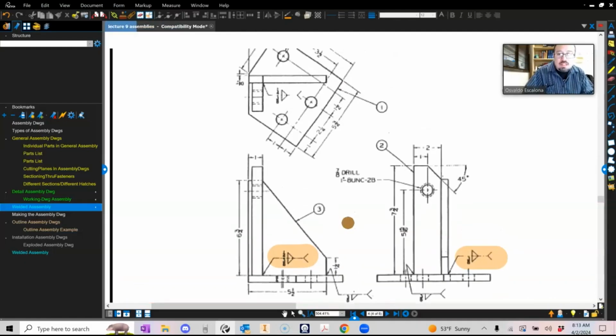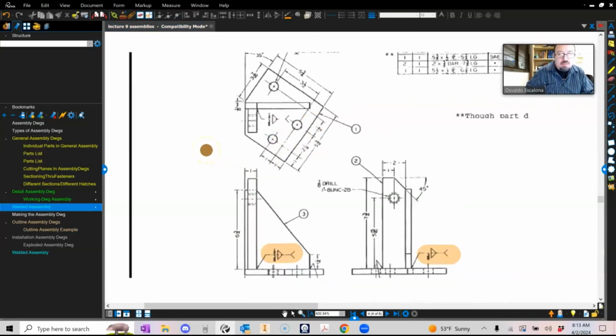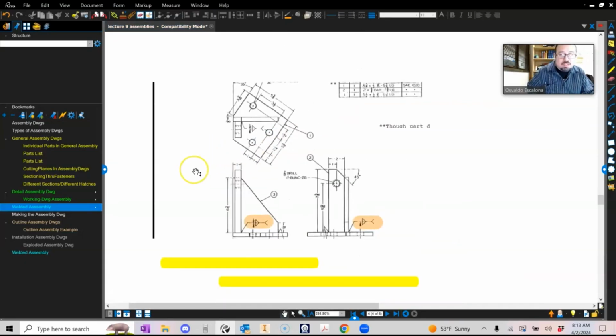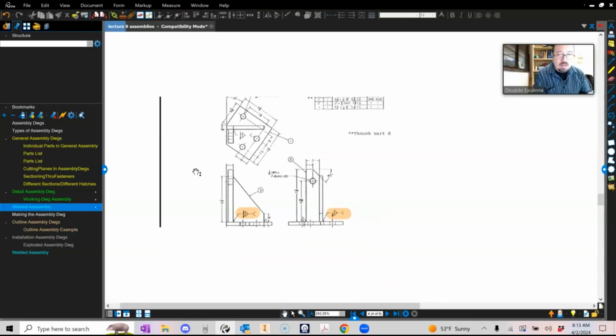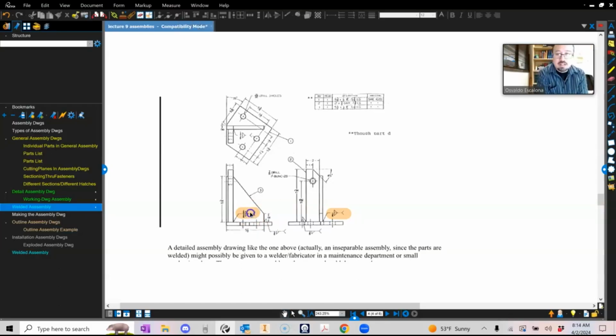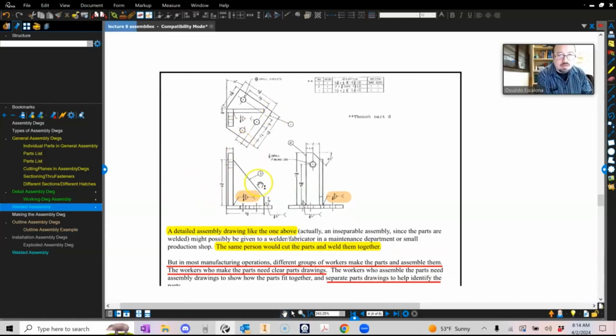It seems to me that this is a detailed drawing because it has all these dimensions within the drawing. It's not something that we do often now. Most likely each part, each drawing will have its own thing. Again, it really depends on where you work, right? When I used to work in the structural engineering consulting firm, we used to create detailed welded assemblies all the time because somebody else came up with fabrication drawings. They will actually separate it and we'll have kind of like similar callouts, but more in terms of how the fabricator will use these drawings.